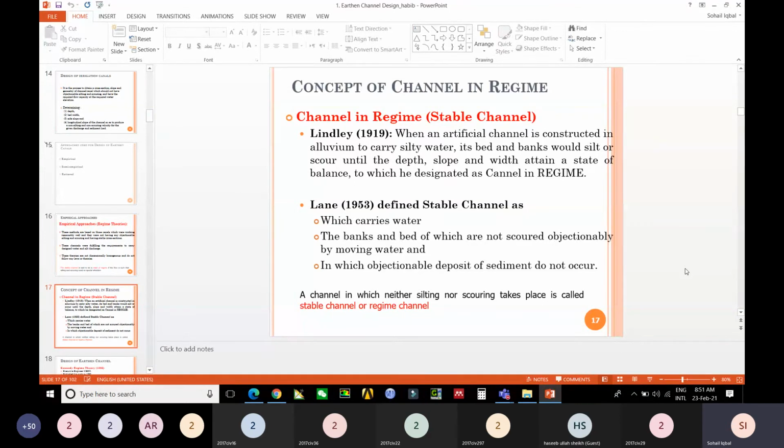The next is Lane, that is 1953. He says that a stable channel which carries water, the banks and bed of which are not scoured objectionably, means there is no objection in it, and if water is moved from upstream to downstream with no objectionable deposit of sediment, then that channel is known as a stable channel.